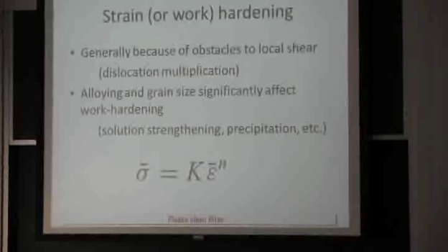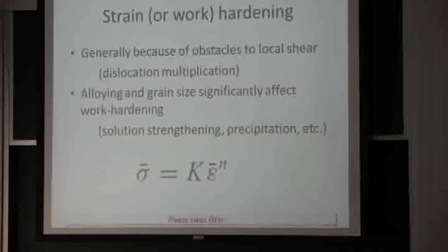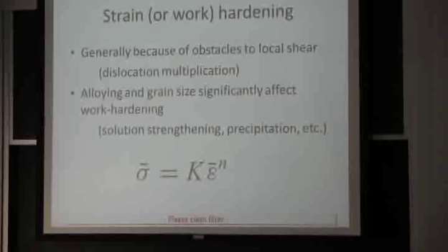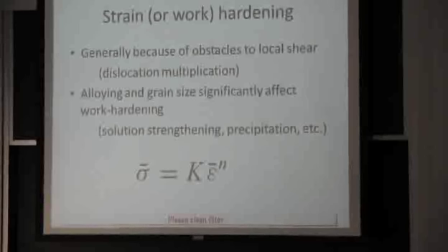So I'm reducing just a little bit the thickness here. The deformation is going to continue there as opposed to going to other locations and making shear at different locations. And some metals, mostly amorphous metal or bulk metallic glass, will have this type of behavior where it doesn't spread much over the distance, and therefore you don't get elongation before you break them.